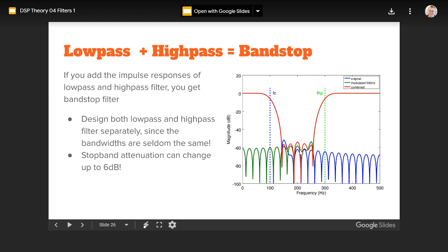And you put those systems in parallel, meaning you are actually filtering with the low pass filter and high pass filter separately and then combine the signals, or you combine the system coefficients. On exercises we have that. One small detail, when you are paralleling systems, then basically these stop bands are added together, meaning that the attenuation gets poorer.